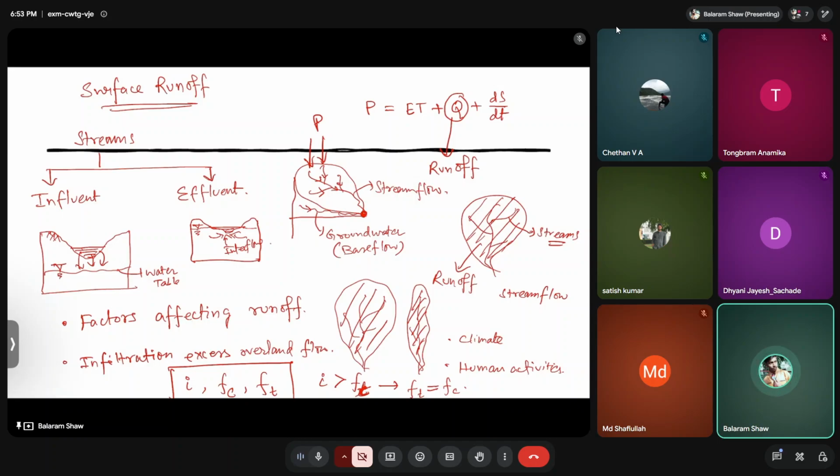Okay, so after water infiltrates the soil on an upslope portion of the hill, the water will flow laterally through the soil and it will exfiltrate. So it will flow out of the soil and it will be near the channel. This flow is called subsurface flow, or throughflow. So if the soil is saturated, then what will happen? Whatever water comes, it cannot infiltrate, and hence it will flow as surface runoff. This we call saturated overland flow, or saturation excess overland flow, or Dunne runoff. Okay, so till this everything is clear, right?